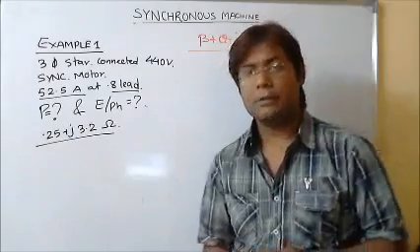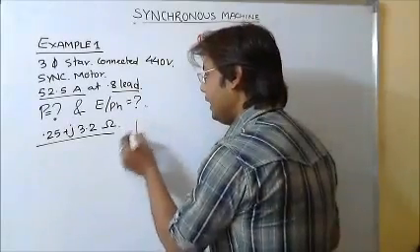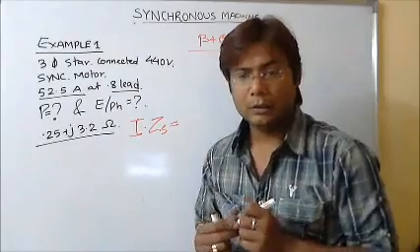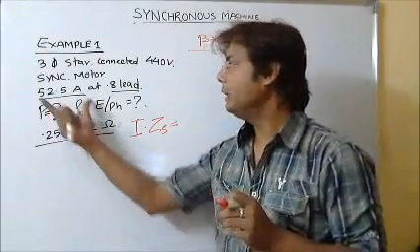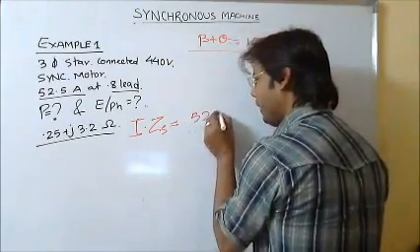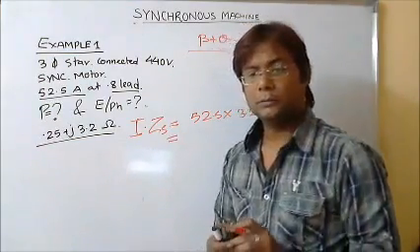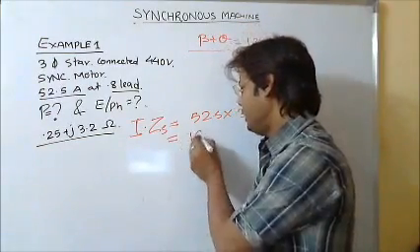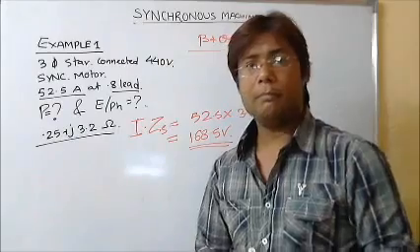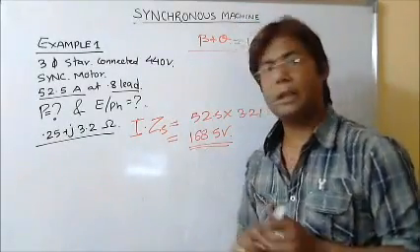Since I got Z equal to 3.21, I can find the IZ drop. That is I into Zs drop, which would be approximately 52.5 is my current and Z is 3.21. So 52.5 multiplied by 3.21 gives me 168.5 volts. So I got beta, I got theta, beta plus theta as 124.9, and IZ as 168.5.